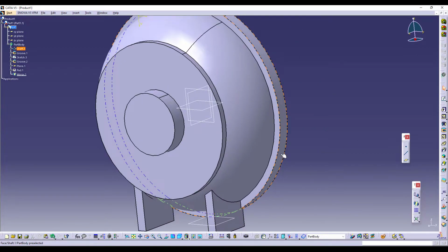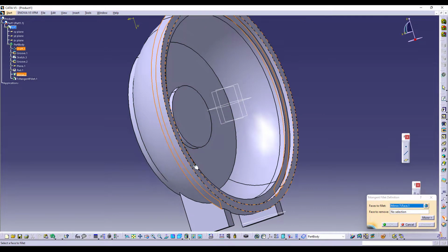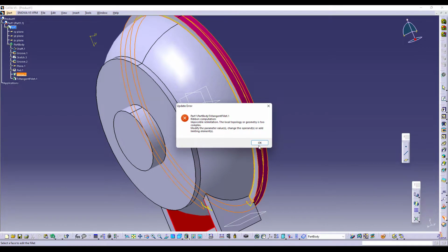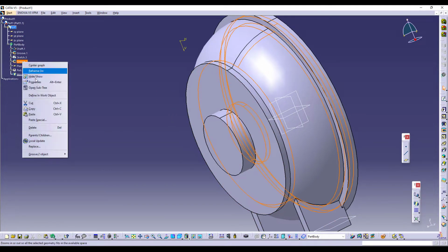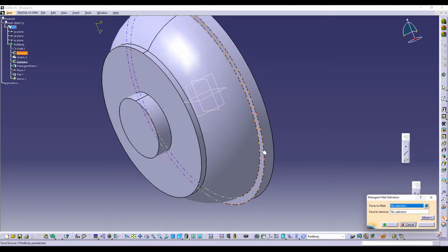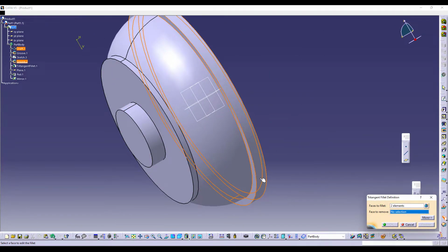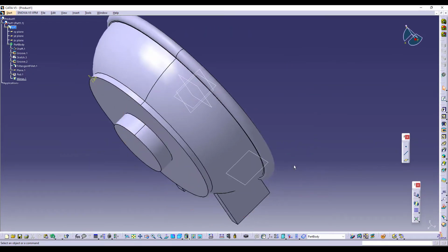Now there's also a full round on this face, so let me try to take that full round too. So my other features will not get affected later on. So in between these two, by eliminating this face. Okay, I should have done that before, so let me go back till here and then try to take the round. The features are dependent on the round, so before that we shouldn't make the extrusions. Now if you go back to the actual one, it just adds up automatically.